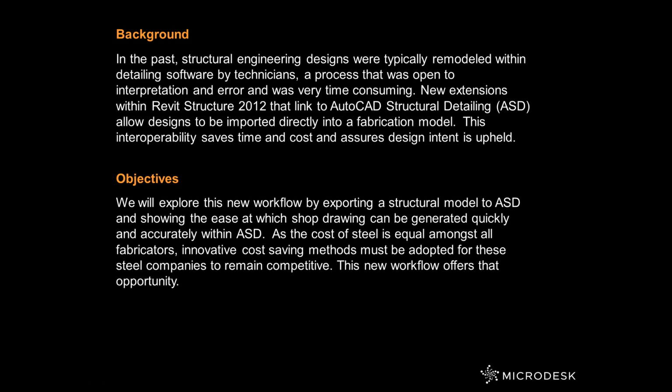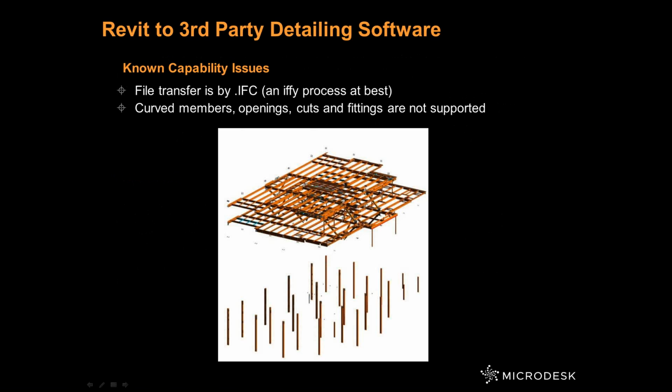Thanks, Ravali. So as was mentioned, in the past, there have been some issues with transferring files between Revit and third-party detailing software such as SDS2 and Tekla. The file transfer between Revit Structure and those third-party detailing softwares is an iffy process at best. Off the bat, curved members, openings, cuts, and fittings are not supported in that transfer.